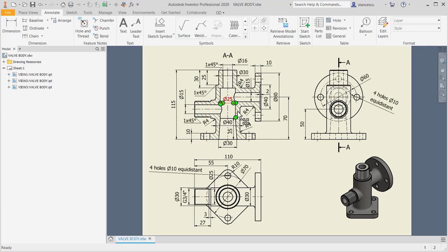There is a vertical revolve feature and two horizontal. Yes, we start with this flange at the bottom, then we create this vertical, then the others, and the last are the hollows. Yes, because you can subtract volumes only after every external features are created. You don't start with revolving external and internal, and then how to connect the internal hollow features. There is a procedure here.